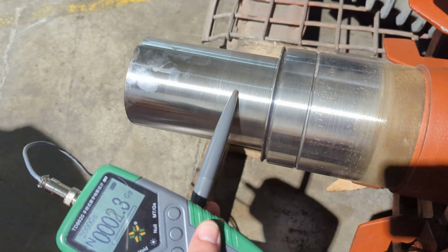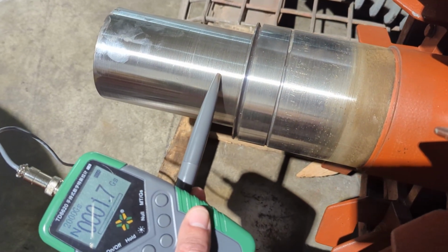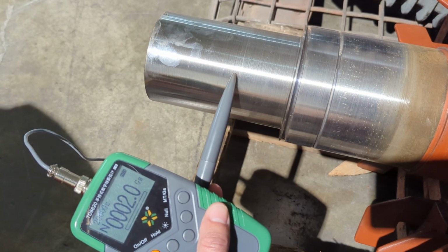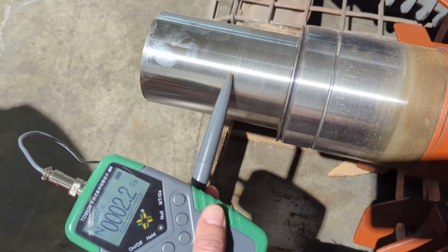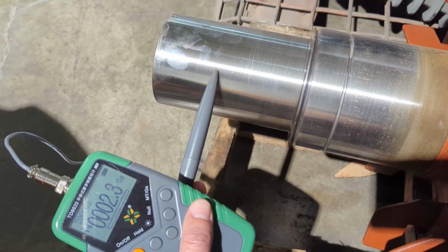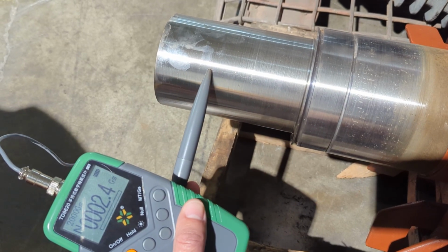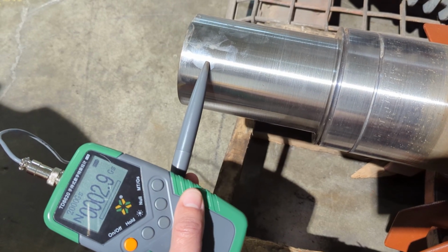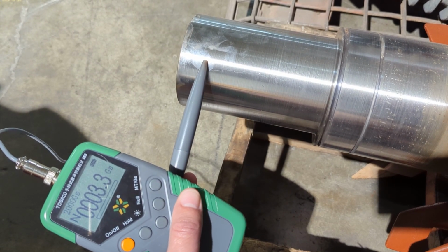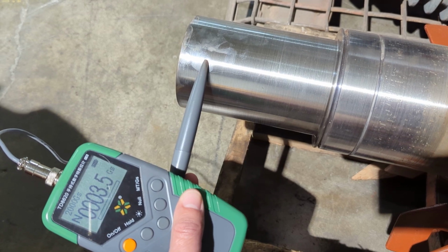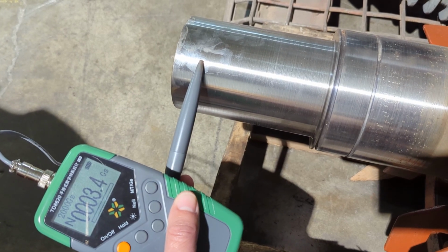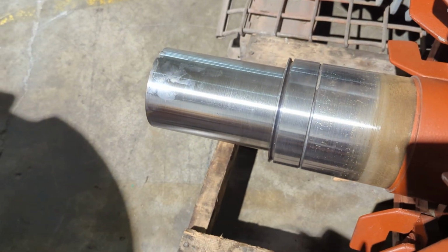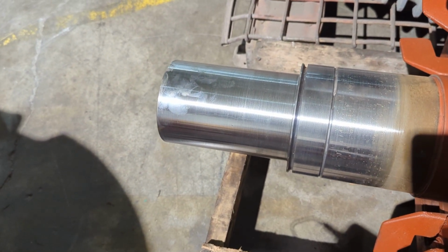It's a radial probe. Put it on the shaft. Oh, look at that. You see, it takes a little bit of time for it to settle. That's normal. Yeah, 2.3, 2.4. 0.9, 3.1. Okay, so now I know this rotor has got a problem with high residual magnetism.